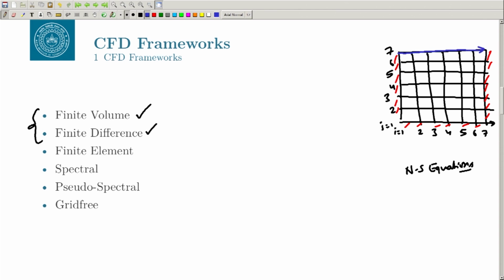Now, let us say I tell you that okay, my cavity is not like this, but let us say I have a triangular cavity. Okay. So, let us say I have a cavity which is like this, okay, or even more complicated, right. Here this lid is moving. Okay. Then if you try to make a finite difference grid like this, you will have problem, okay, because at this point, this corner you will have the singularity, right. So, if you want to solve the same problem, basically the governing equations are the same, the Navier-Stokes equations, okay, and then you have a lid moving, okay, but if you want to solve this using a very nice grid like we have done for this square cavity, it will be very difficult, right.